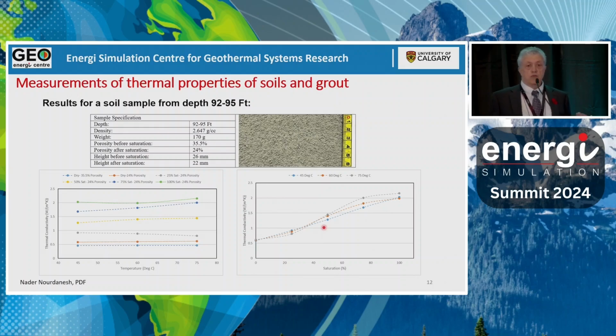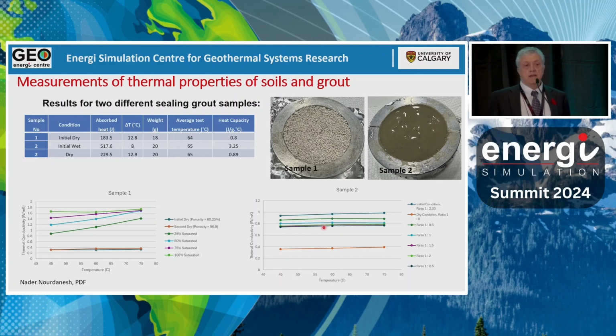Then, once you have those, you can put them in some kind of fitting model, or give them as tables you can put in your modeling that will do the heat transfer calculations. But over and above that, we have material, grout, that is put inside these little wells that will do the geo-exchange, and those have their own properties as well. Grout 1 and grout 2 don't look the same. Therefore, their properties are not the same. So we have to do the same exercise for those.